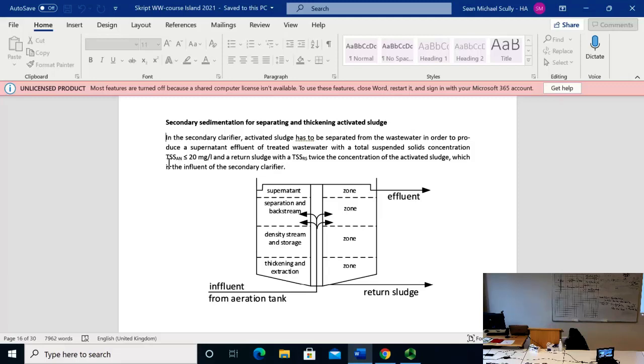But by moving the sludge around here, you also get a little bit of dilution by the water from above. But when you suck it away, then of course you have the high viscosity, because most of the fast-sedimenting sludges accumulate here and will thicken more. If you have the suction scrapers, the hoover, you can hoover more thin sludge from this side than the thick sludge here. And due to that, you have more unwanted dilution for technical reasons due to the scraping.